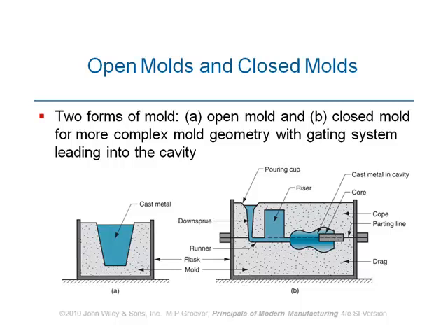And then this material has solidified. After this, it's the riser which solidifies. And as a consequence, there could be some void spaces produced in the riser instead of the part, which is not important because we are not interested in what we produce here.